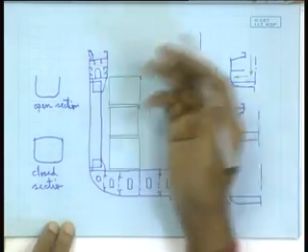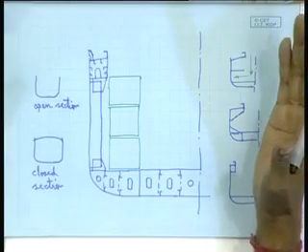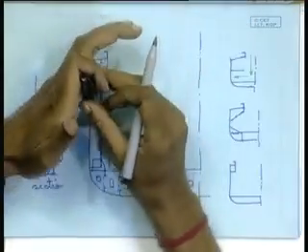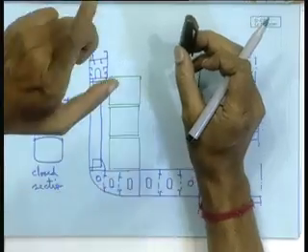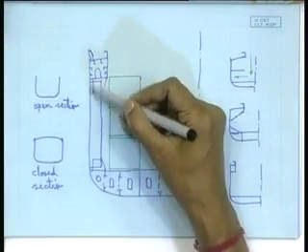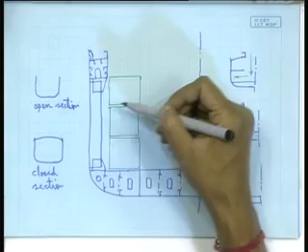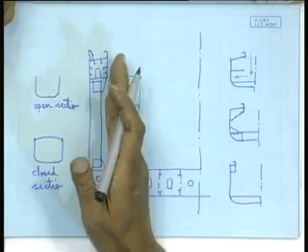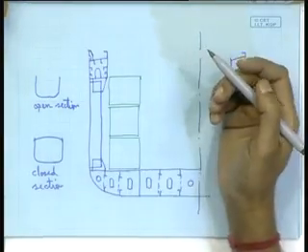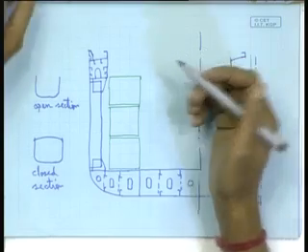How small? Well, obviously it has to be enough such that it gives a good walking space, because you'll have to probably walk from the fore end to the aft end, all that. And plus, well, it cannot be just the single skin of the hull, so there will be stiffeners inside, so that much space. So it could be as less as 1.5 to 2 meters even, right.